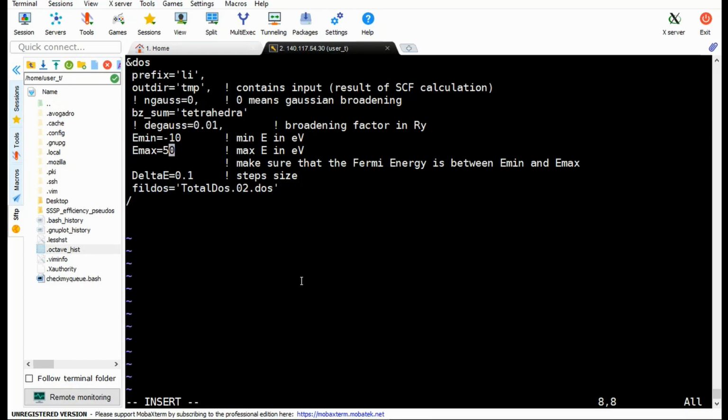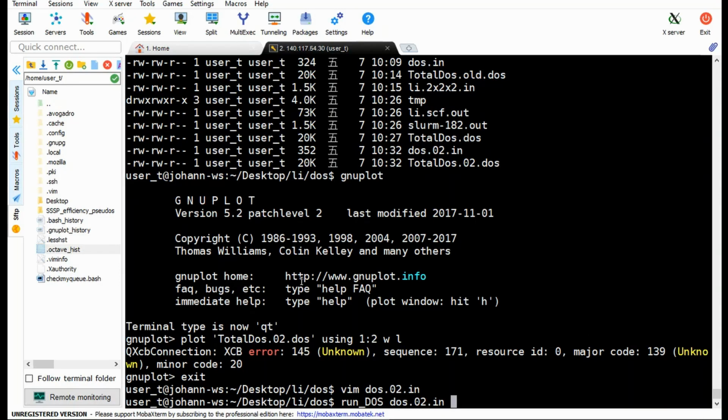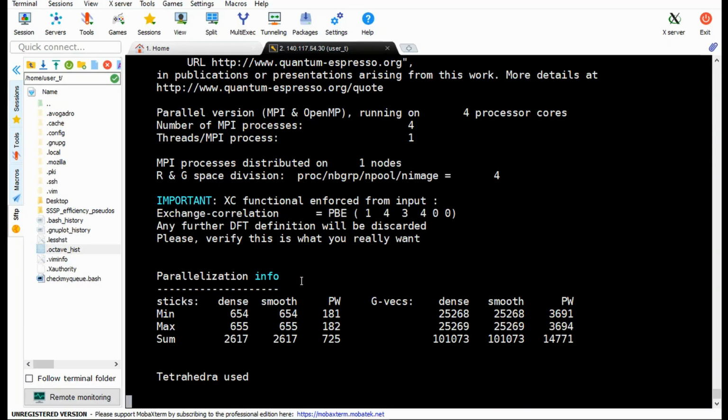So, okay, now we are a bit more reasonable here, right? So we go from minus 10 to 10 eV again, and we decrease the step size to 100th. Right, so there's one more good advice. If you give the density of state in a report or paper, you don't want to have it look like this, okay? Not so spiky. You want to have it more smooth, right?